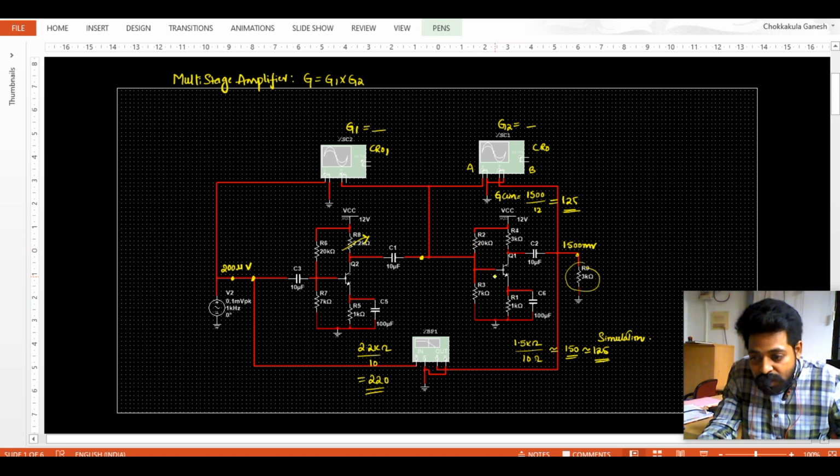So if I do it, there will be an input resistance over here. It is HIE, and this network is totally shorted once we have a bypass capacitor over here. So from this point to the ground I have a HIE, and the R1 network and R2 network are connected as they are. Once you go with the AC equivalent circuit, where I have to calculate the AC input resistance, VCC is connected to the ground itself, so 0. So this also will come to the ground. So now from this point to the ground, all three come in parallel.